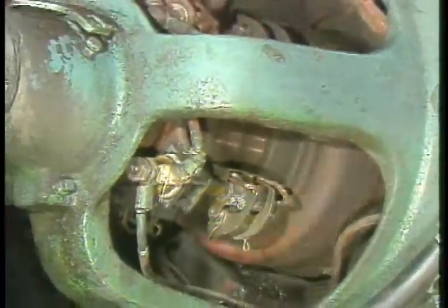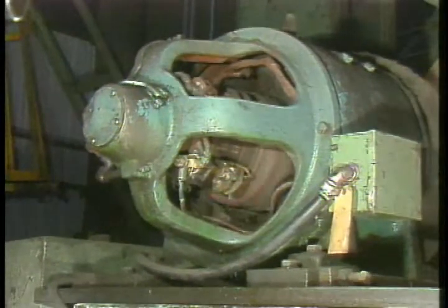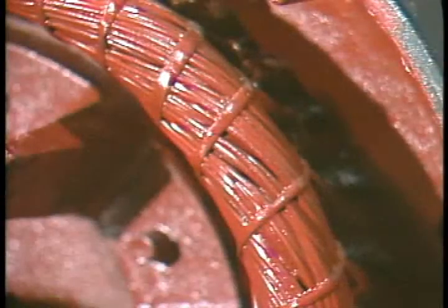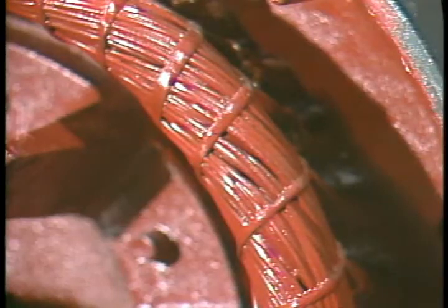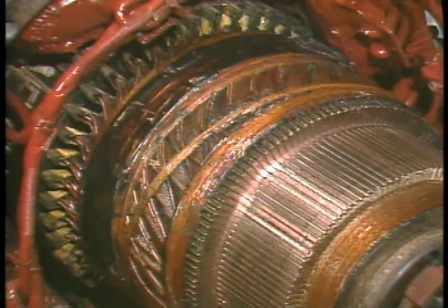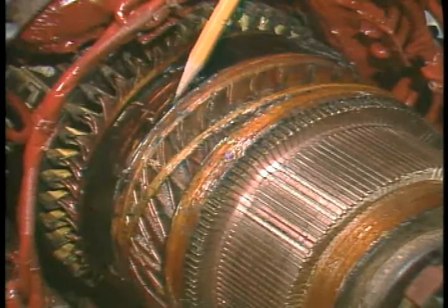Another reason there is so much steel in a motor is that the air gap between the stator and the rotor must be accurately maintained so the rotor does not rub on the stator. The frame must be strong because the windings inside a motor are subject to high forces. Magnetic forces on both stator and rotor windings can actually force them out of position. So windings are lashed securely in place to prevent any movement which might chafe through the insulation. Rotor windings are subjected to centrifugal forces as well and are often banded to prevent them from flying out of their slots.